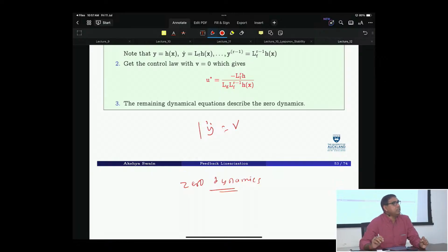The input-output linearizing controller must study the zero dynamics. Those dynamics which you eliminate, you don't just ignore, you study them, otherwise there will be a problem. If you ignore some people, it's horrible stuff. So the zero dynamics must be stable. It is the dynamics of the system when all the state variables which are being linearized become 0.